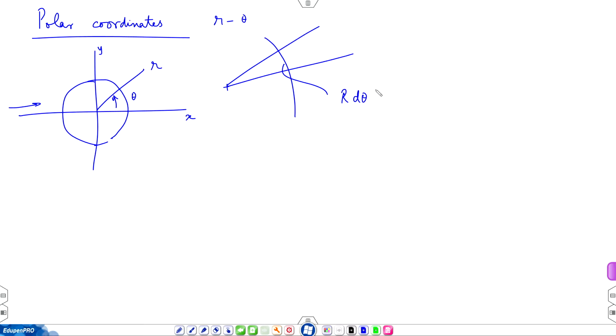Okay. So, you can construct a fluid element in r theta coordinates and show stress components sigma r r, sigma r theta. Sigma r theta is the stress component on the r face in the theta direction. So, it is a shear stress. Now, you will have another sigma r theta on the inner side. So, after all you want to find forces. So, these crosses indicate the surfaces that are going to be in contact. One is from the fluid side and one is from the solid side.